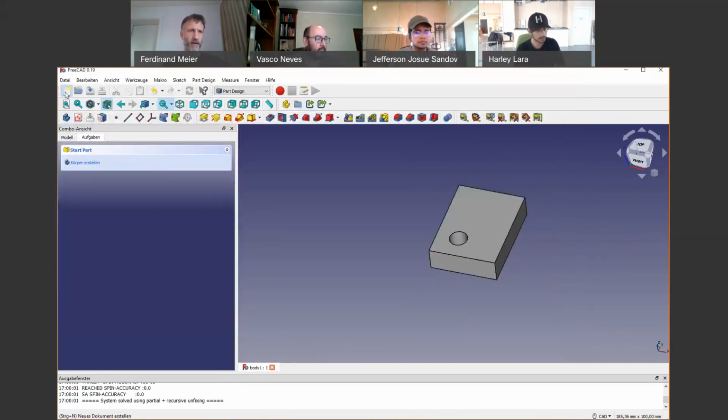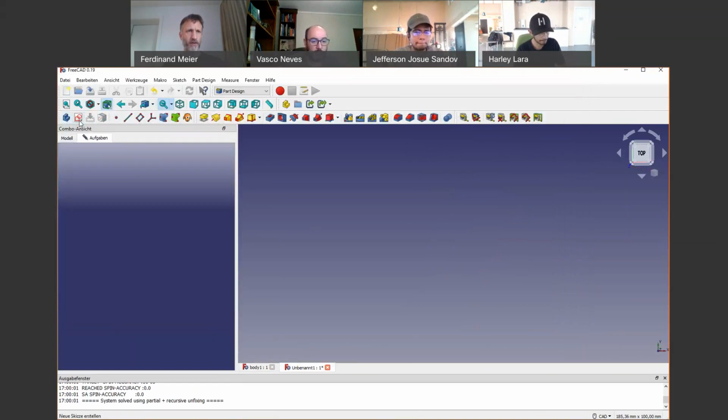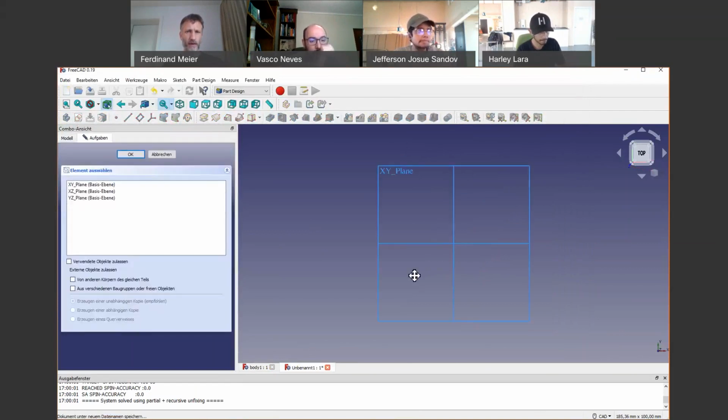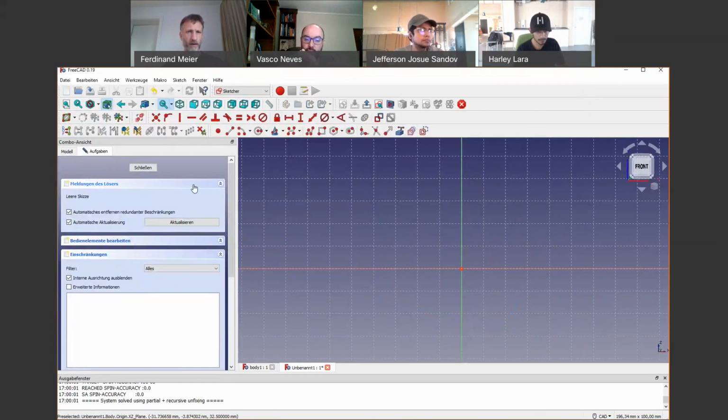And I make another file. New body, new sketch. And this time I select the XZ plane. And just for a change, I'm going to draw something that is like a rotational object.